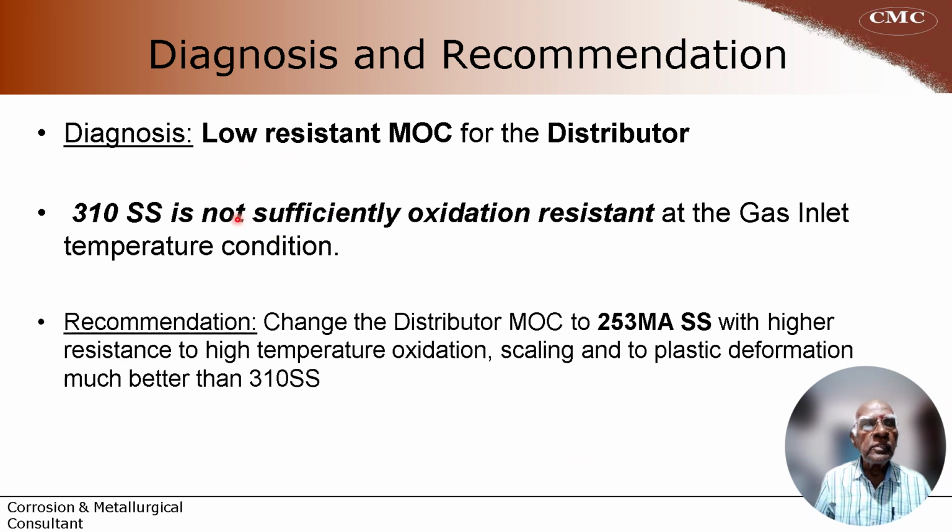In general, 310SS is a high temperature grade, but for this condition, it is not sufficiently oxidation resistant. So the recommendation is to change the distributor MOC to 253 MA, which is a special grade developed to withstand higher temperatures than 310SS, with higher resistance to high temperature oxidation, scaling and to plastic deformation, much better than 310SS.